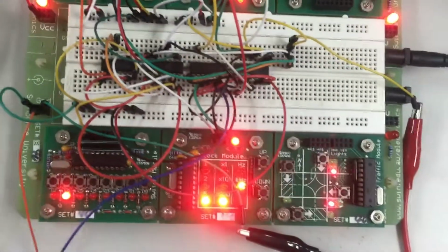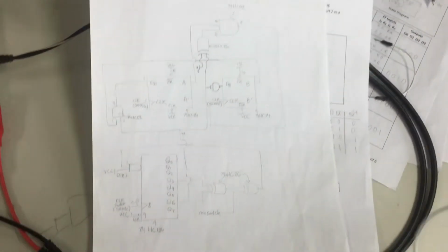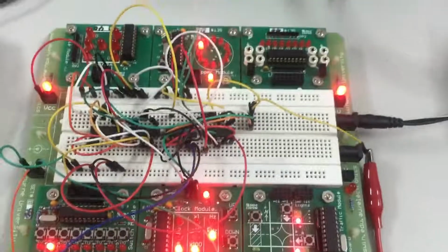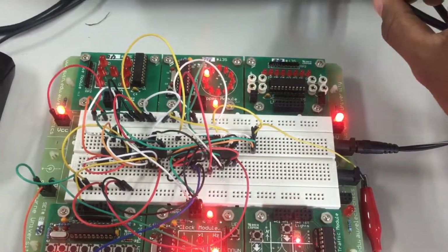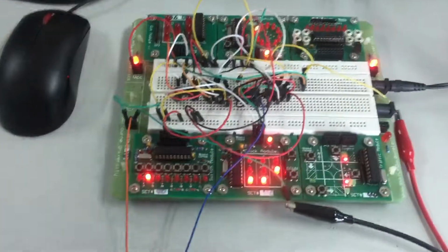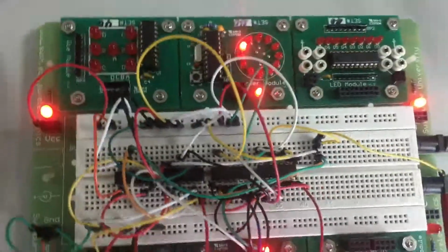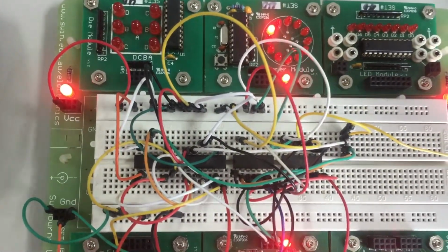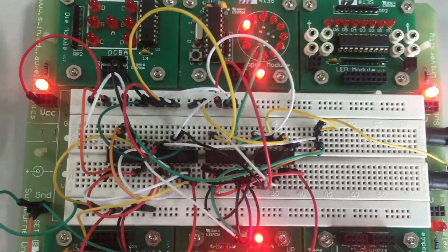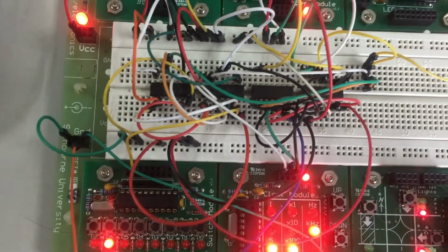After putting all this into our board over here, these are the schematics we have got here. As you can see, the input is connected to channel 1, and the output is connected to channel 2. This is our run switch, which is on now, and we have set the frequency to 500 kilohertz. In this case we have used 4 ICs, which are the HC74 IC, HC86 IC, HC00 IC, and HC08 IC.